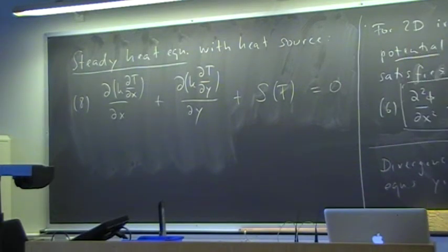So if we would have the full energy equation, we would have the time derivative of rho Cp T, and we would have the nonlinear terms, which give us the effective transport. But if we only look at this situation where we have a steady state and where we assume that we have no motion, so the velocity is 0, then we have this form.